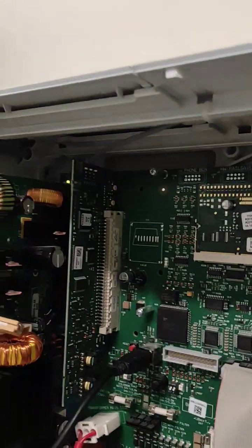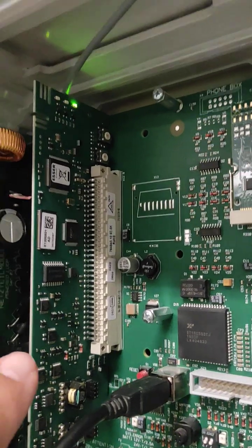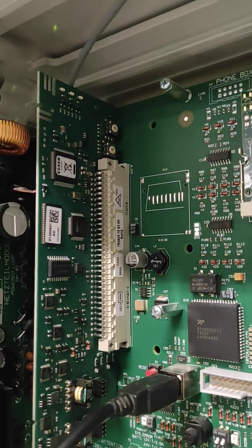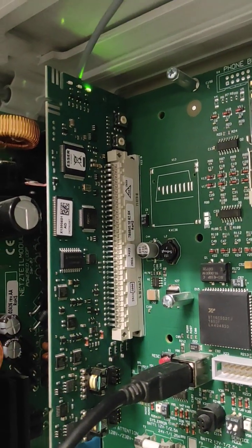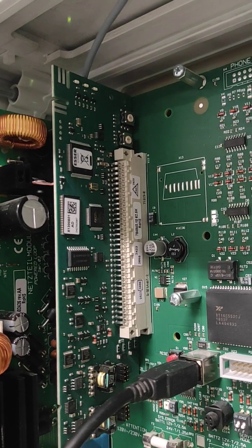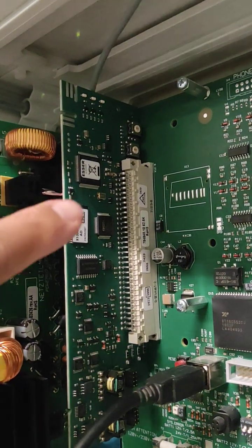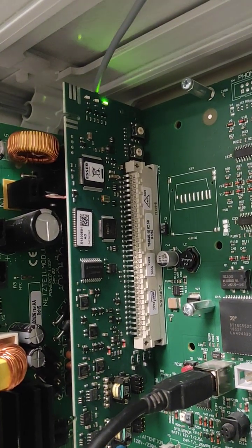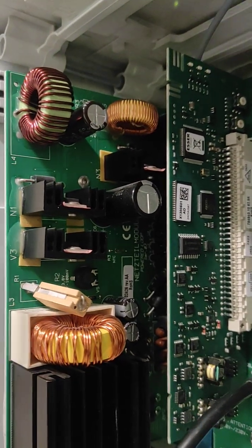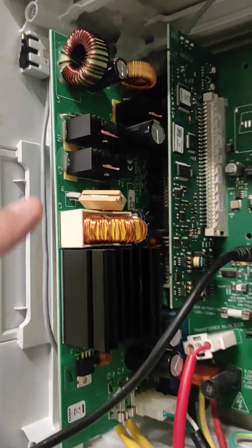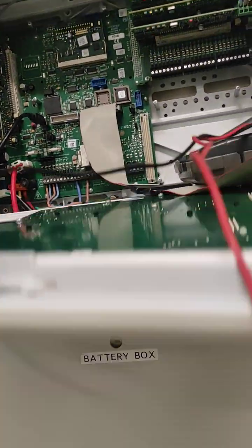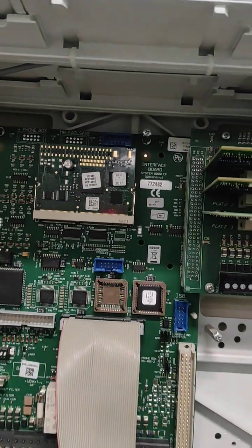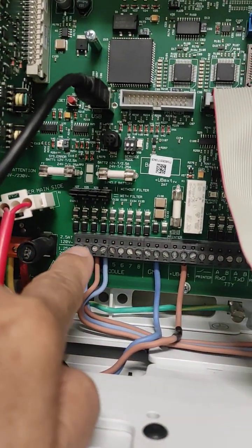This is the network, or what we call the Ethernet, 500 KBD and 62.5 KBD. If you are using 62.5 KBD, you can connect up to 16 control panels in a network. But when you are using 500 KBD, you can connect up to 31 control panels in a network. This is the power supply, for the battery charger and everything supplied to the circuits. This is the CPU, central processing unit, and this is the connection to the network.